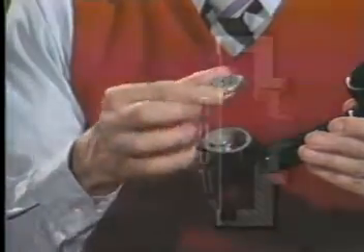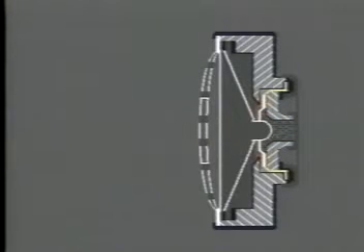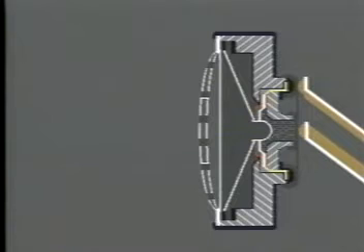The most common telephone transmitter in use today is the carbon transmitter. It consists of 3 major components: a chamber, thousands of carbon granules, and a dome-shaped diaphragm. When the handset is off-hook, these 3 components become part of an electrical circuit which is supplied with direct current from the central office.